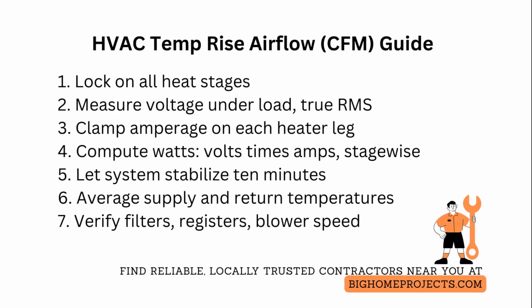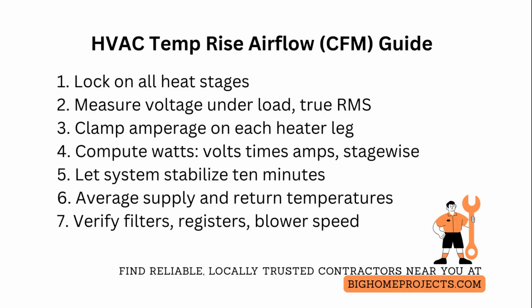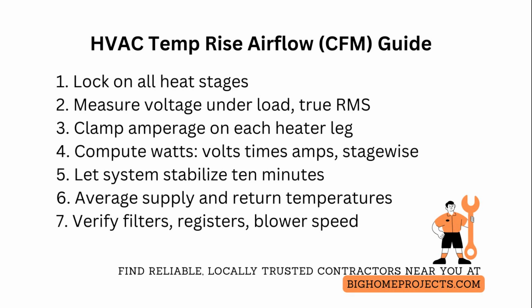Finally, use the airflow formula. Cubic feet per minute equals 3.16 times total electric heat in kilowatts divided by temperature rise in degrees Fahrenheit, where 3.16 is the conversion using standard air density. For non-standard conditions, adjust density or use psychrometric correction.